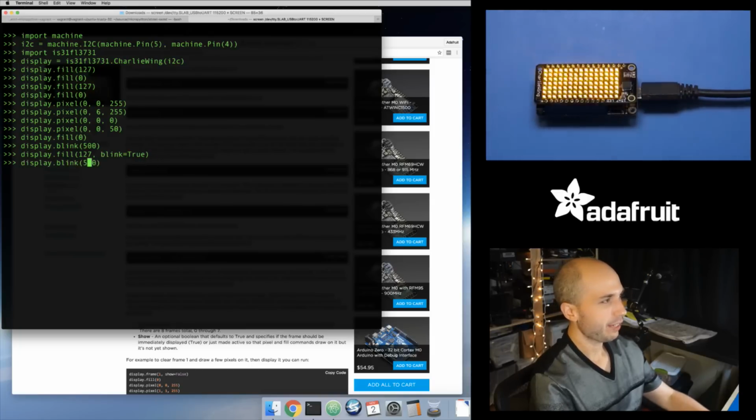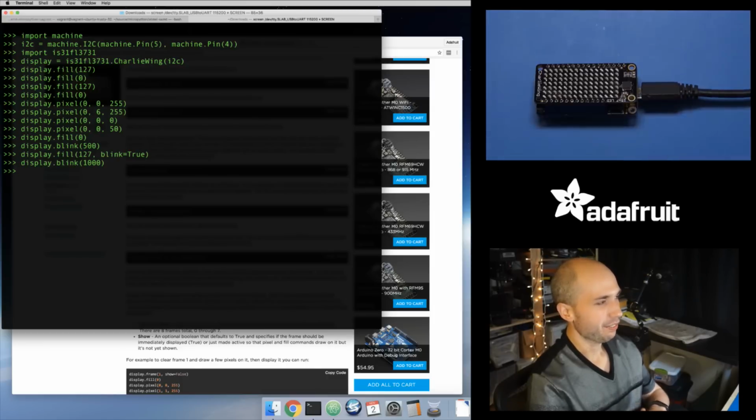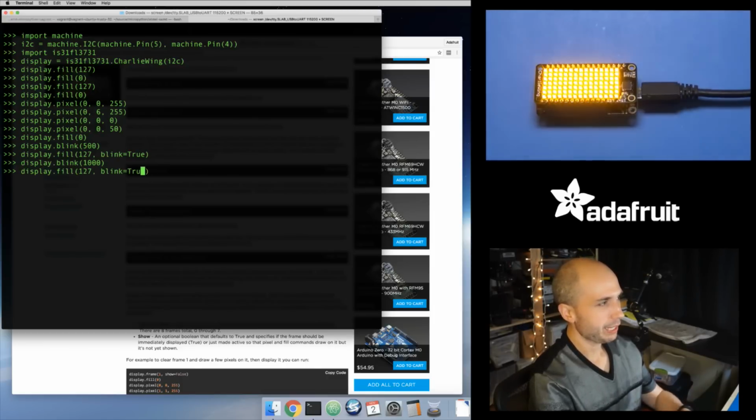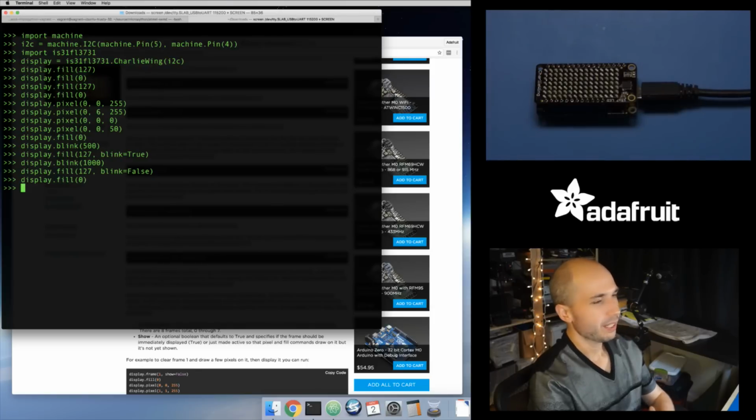And if I want, I can change that blink rate to, let's say maybe 1,000. So it slows it down a little bit, so you can see it's blinking at a different rate like that. So that's kind of cool. And if you want to turn off blinking, you just set blink to false on all of these. So it goes to false. And then maybe I'll clear the display again. So we'll say display fill 0.